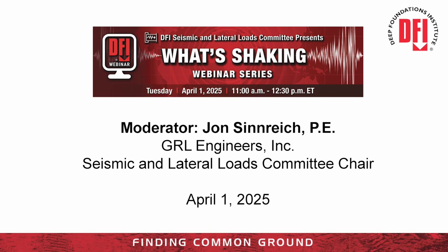The Next Generation Liquefaction NGL project's supported modeling team, SMT, was tasked with the development of new probabilistic liquefaction models. This presentation discusses the SMT's approaches to, number one, use the extensive NGL case history and laboratory test results database to perform analyses that previously would have been logistically impractical, and two, to develop relationships required to compute the probabilities of liquefaction susceptibility, triggering, and ground surface manifestation.